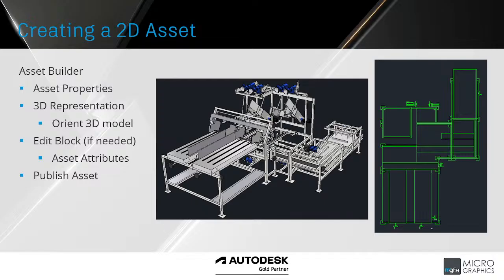Now you don't have to, but if you are wanting to go into Inventor with your layout, you then are required to, or you would want to have a 3D representation that is aligned with the block. Now, we'll see in the demo when we bring in the 3D representation, we do need to validate that 3D representation and get the position aligned correctly with the block.